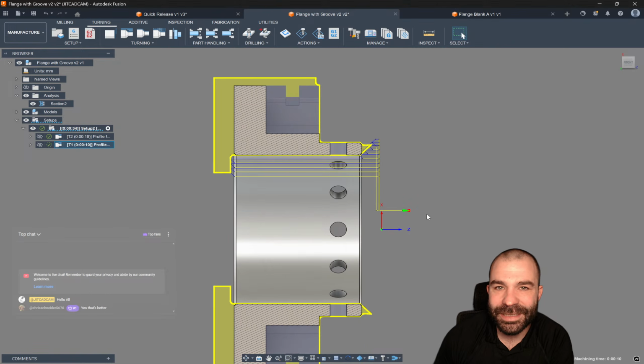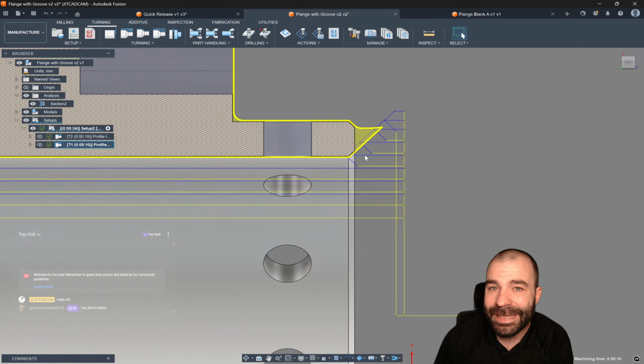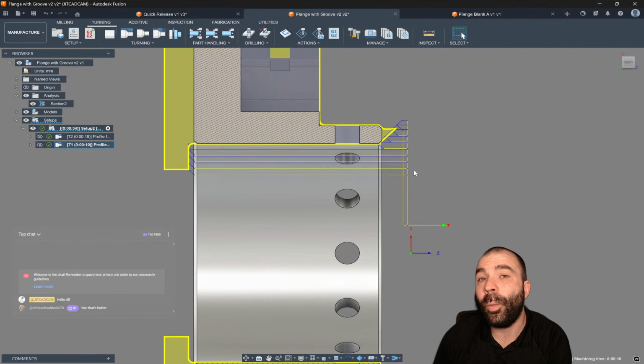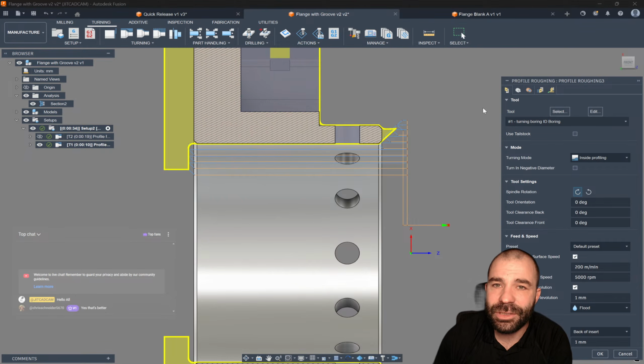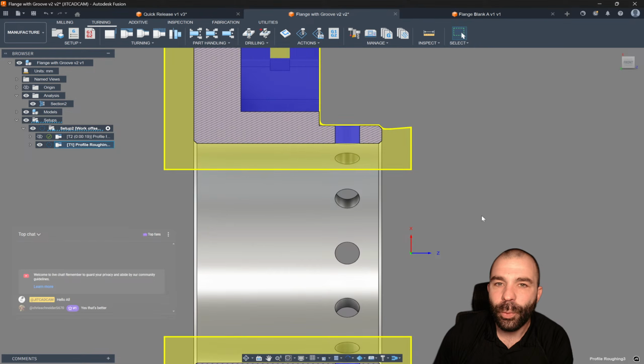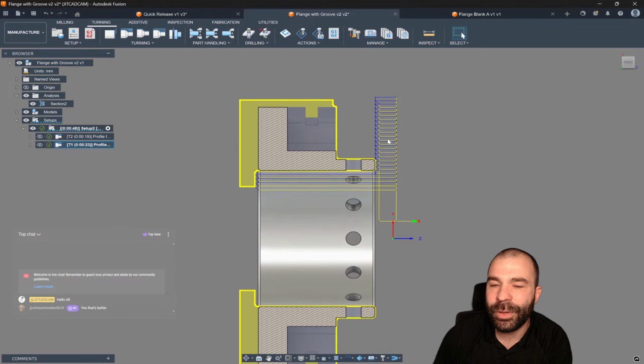And what you're going to notice is now our tangential extension is going to miter because, again, we are tangentially extending the chamfer right now, right? Some of you are probably questioning, well, wait a minute there, Fusion Phil. Tangential extension is waterfalling and undercutting the part. Why not use offset? Well, had I used offset instead of tangential extension here, so let's zero that out and put 5 millimeters in, what I've done is I've now allowed the tool to come around the part and not be trimmed at the tangential extension segment, right?